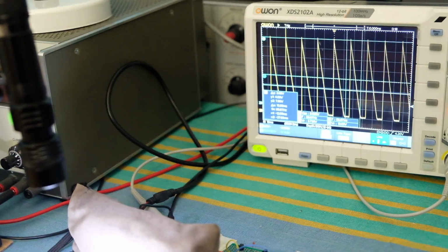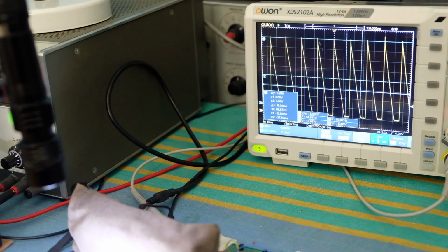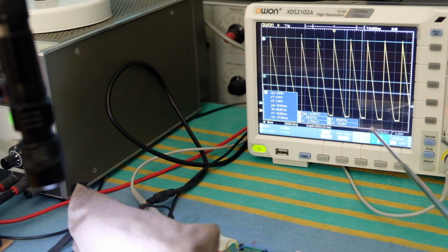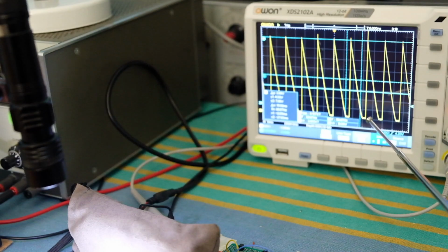Oh wow, now look at that. That is going to be fully saturated. As you can see, the waveform has hit the bottom rail, and that means I need to increase the capacitor a little bit to be able to measure this properly, but I'm losing quite a bit of the signal because the capacitance is completely full in terms of the charge.